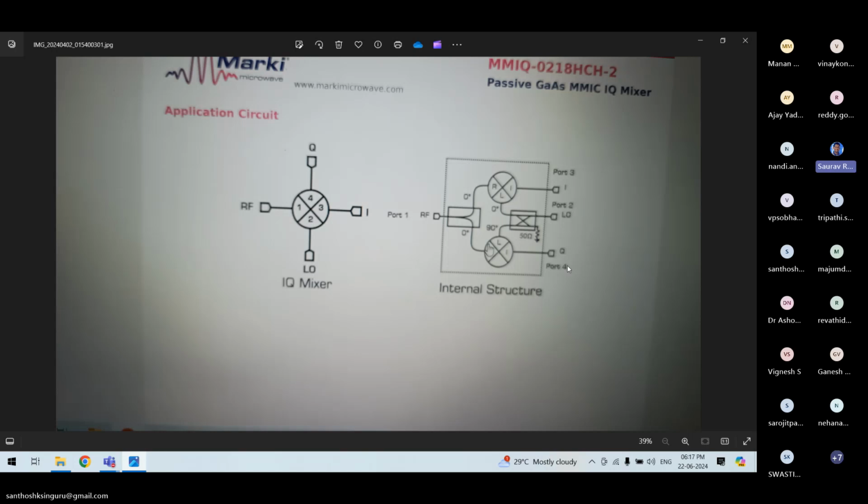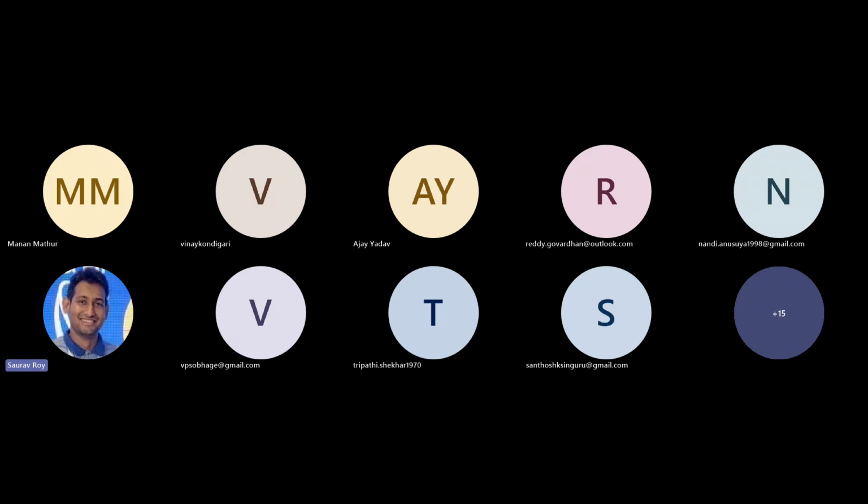But here, the frequency is fixed. Only the phase of the carrier signal gets shifted. That is quite different from here. So there is no I and Q here. I and Q come in communication systems. We are talking about the phased array system. There we don't want frequency shift. Frequency is fixed all the way. Okay, so I will go back to my thing again.